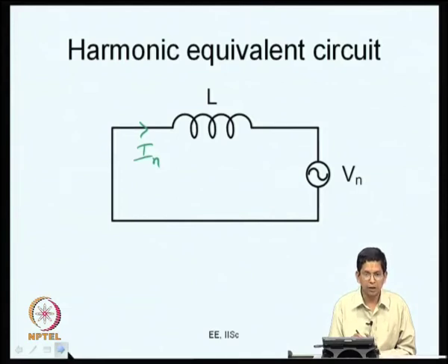That is, first we are able to calculate harmonic voltages. We are considering a voltage source inverter which applies certain voltage waveforms. These voltage waveforms are periodic waveforms to the extent we have considered, but they are not sinusoidal. So, we know how to calculate the fundamental and harmonic components, that is, the Fourier series helped us. And once the harmonic voltages are known, the harmonic currents can be obtained through the models we just discussed now.